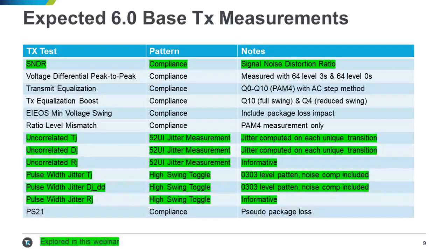So you can think of it as a compression from one side or both sides. It gives you a very narrow pulse, right? You could think of this as maybe you have a single or small amount of transitions. Let's say maybe one pulse wedged in between two lower frequency regions, right? That usually results in a very compressed pulse. And so PCI Express is unique in that it has this measurement.